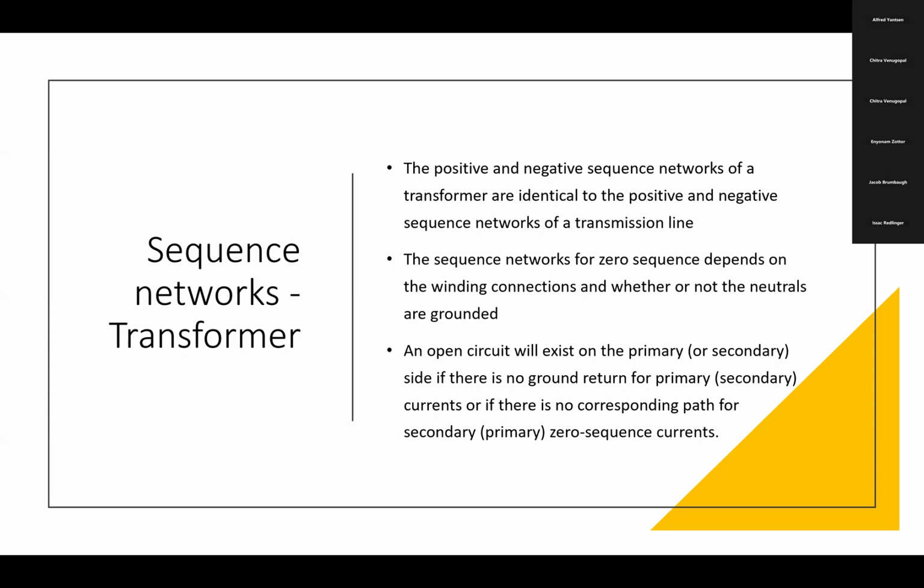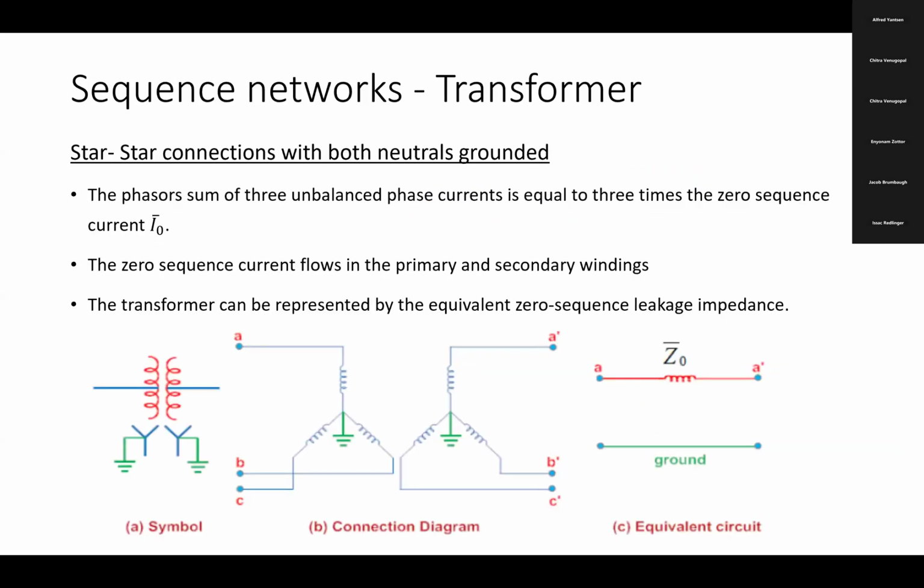You can read it. I will take it to the diagram. It's just the zero sequence when things get different. The zero sequence things are a little bit different for delta and Y connections because the ground connection does not exist in delta, whereas it exists in Y connection, because we are talking about three-phase transformers, not single phase. Okay, right. So let's start from star.